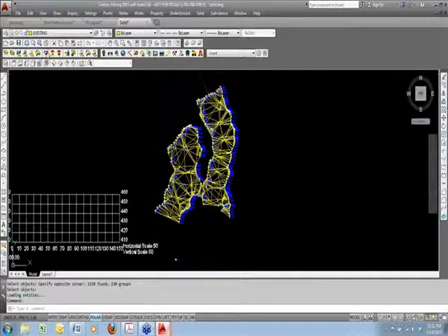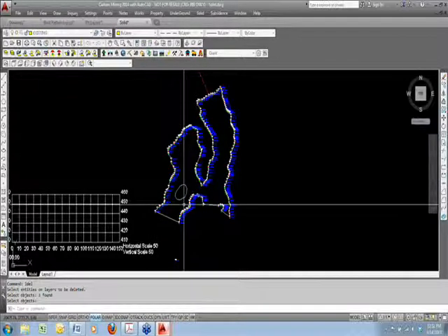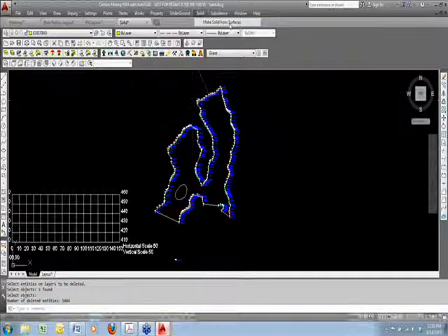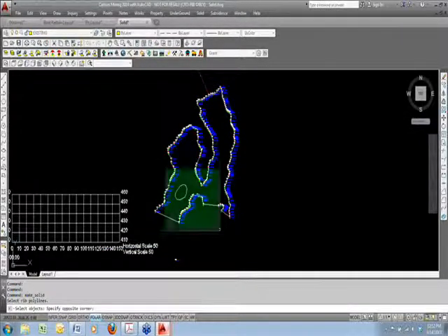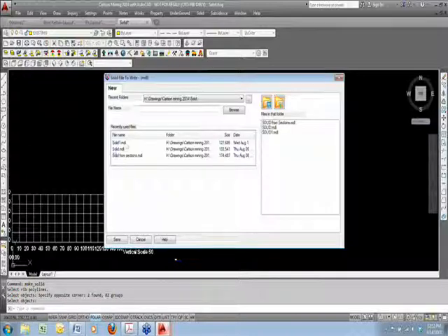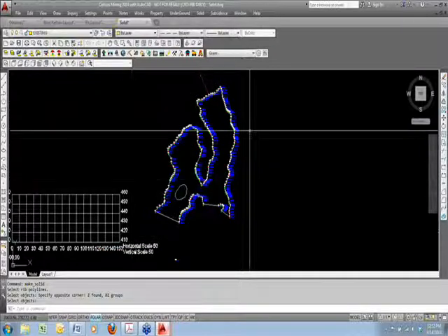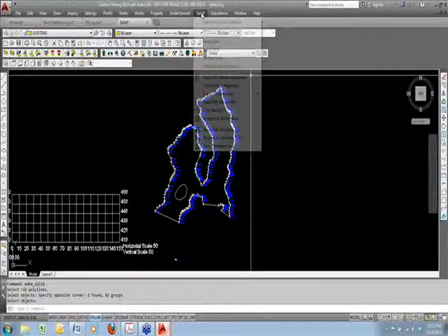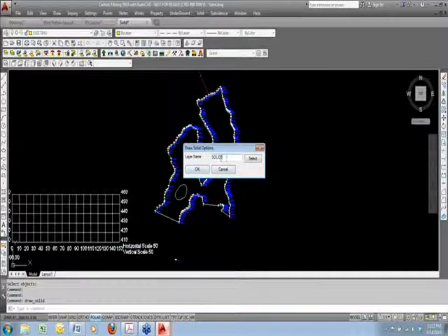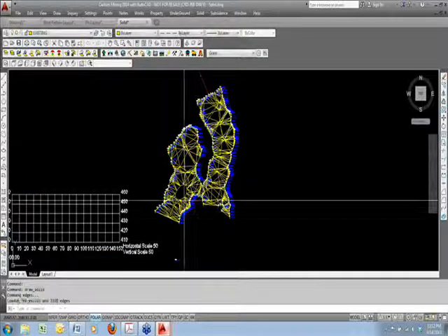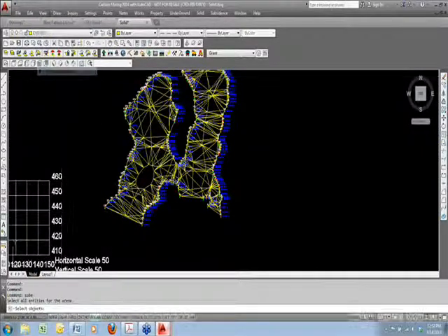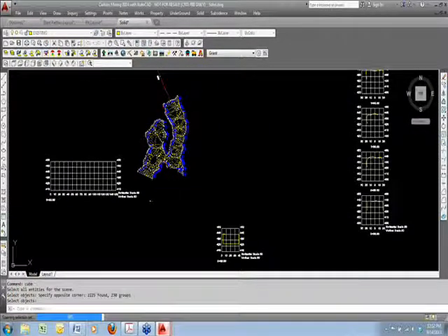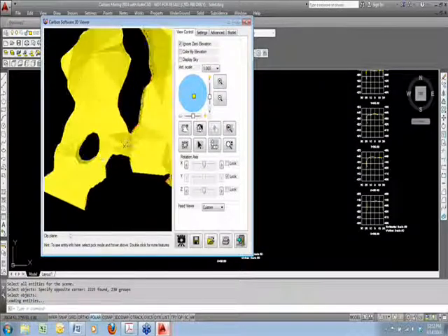I'll just delete layer, and then I'll run it again, solid from surfaces, choose the top, and then the bottom, and then I'll choose both of those polylines. And I'll call this one solid 2. That'll have the exclusion. And then we'll draw it, and you should see, we'll call it solid 2, the opening, like so. And then we'll just take a look at that in 3D with the 3D viewer window. So these are just 3D faces, triangulations, and there it is.